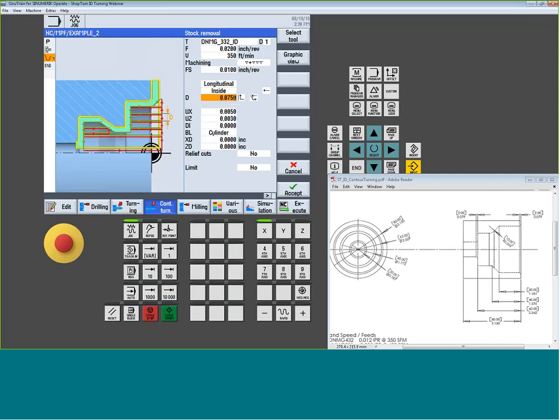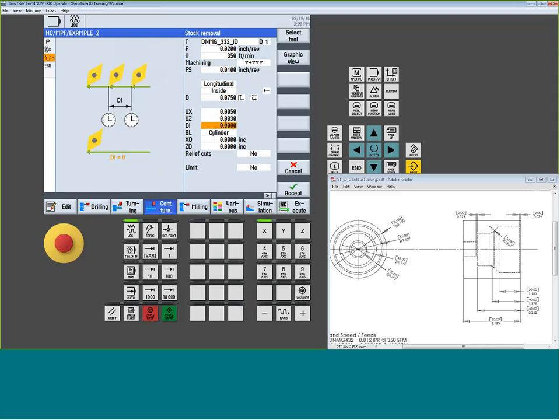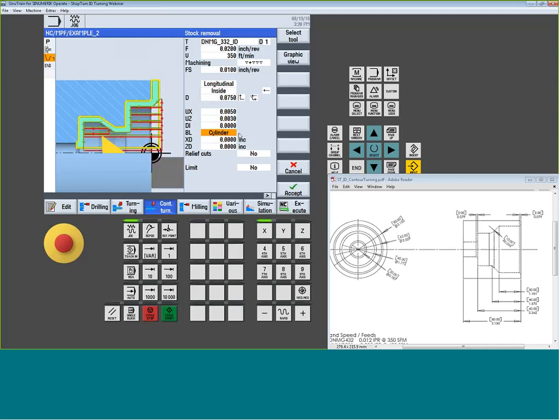From there, depth of pass like I normally would use, amount of material I want to use for the automatic finish pass, if I want to do an interrupted feed. Now, cylinder is important, as it always is. This is saying I'm going to be doing some kind of box. Now, it's not using the stock to figure out where it has to machine. So the blank that we described and things that have been machined, it doesn't track that. It's using this right now. So I have 3 options to tell it what I'm machining from. I'm doing a cylinder or a bar. I'm doing an allowance, so the part's already been machined, but I just want to clear off a little more material. Or I'm drawing a shape that denotes the stock.